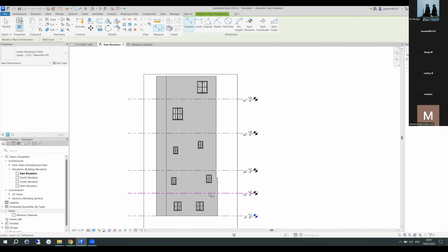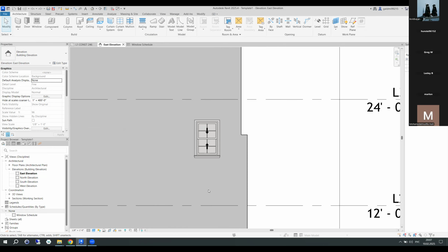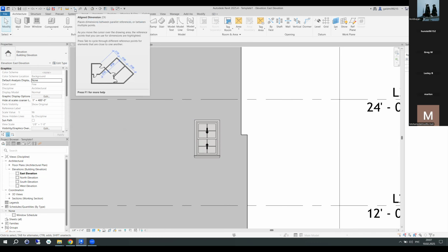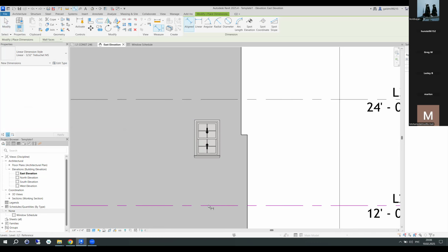So from level 2? Click there, zoom way into that window before you click. Zoom it. One of the biggest things when using dimensions is you really have to make sure you're close to your work, because right now you've got 12 feet between those two windows. That's a lot of distance, right? So if there's a reference plane or something that's trying to snap that's a half inch lower, it's really hard to tell. So let's click that dimension, click the level plane, so level 2, and then